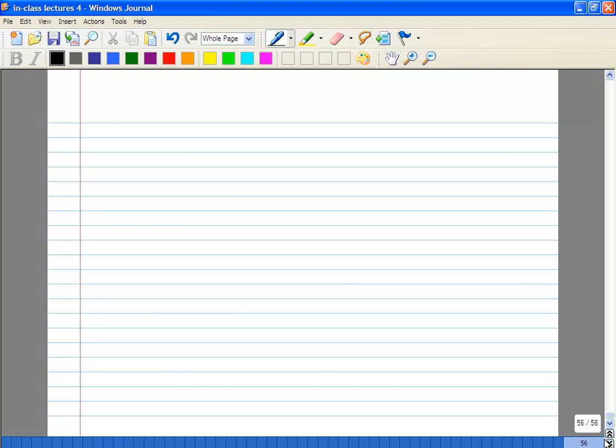There are a couple of other circuits for increasing it, okay, we won't worry too much about it. So now we have considered a single stage amplifier. Now suppose you want to get a very large overall gain. Okay, we know that a single amplifier has a gain bandwidth product, which means if you get large gain, you'll get low bandwidth and vice versa. So now you want to get both large gain as well as large bandwidth. The easiest way to do that is to cascade many stages. Okay, so let's look at that.